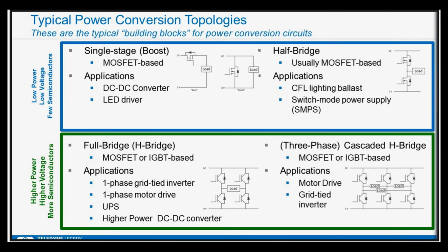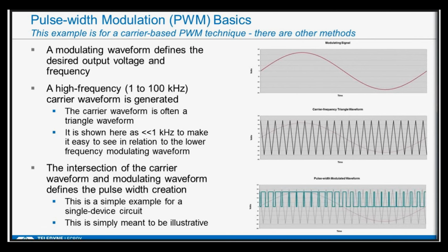You increase the capability of the drive or the power conversion circuit a lot, and you don't increase the cost all that much. So 3-phase is very common on motors, especially, and even very small motors, where you might think they don't need 3-phase because they're such low power, but they utilize 3-phase for control characteristics.